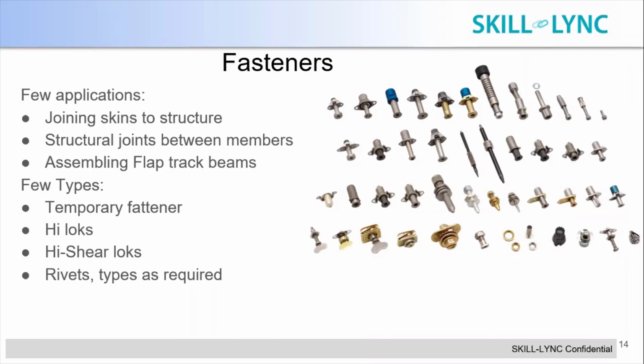Like you might have seen bolts tightening with nuts to join any of the mechanical members. But there are a few fasteners where we use the hexagonal or the surface gripping head. Once we tighten the gripping head and attain the required torque on the fastener, as per the design, the head rips off. That's called a shear lock. Just to give you a heads up.